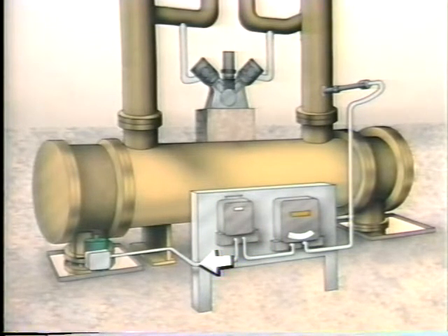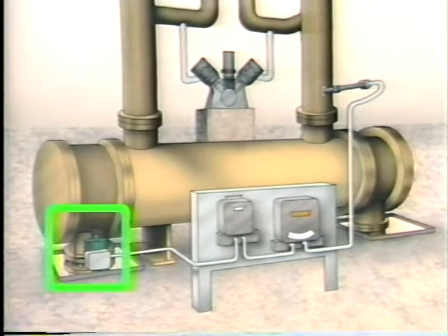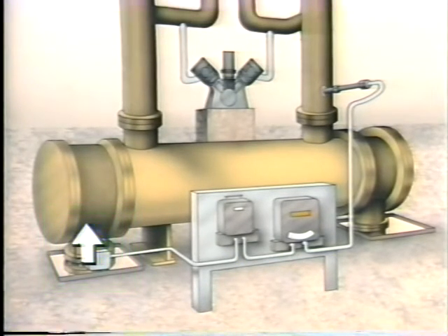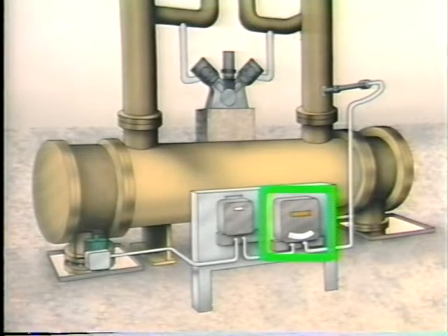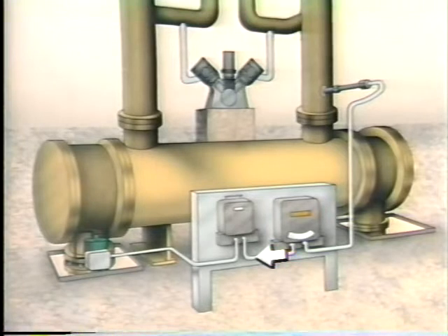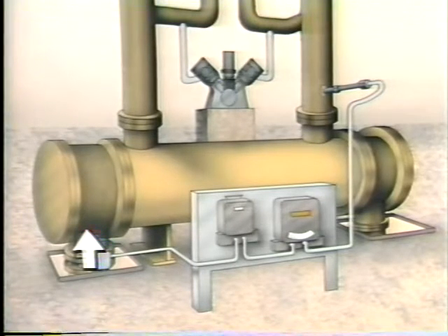The new controller output adjusts the valve to increase or decrease the flow of raw water through the heat exchanger tubes and change the temperature of the cooling water. The transmitter continues to sense the temperature as it changes and feeds back a signal through the control system to manipulate raw water flow until the cooling water temperature returns to set point.